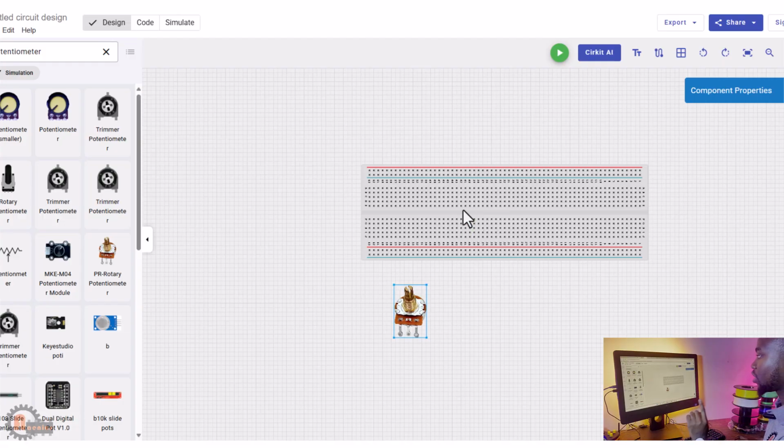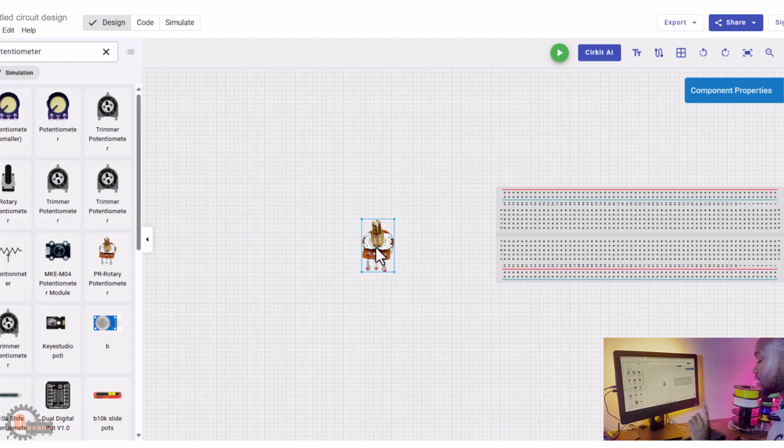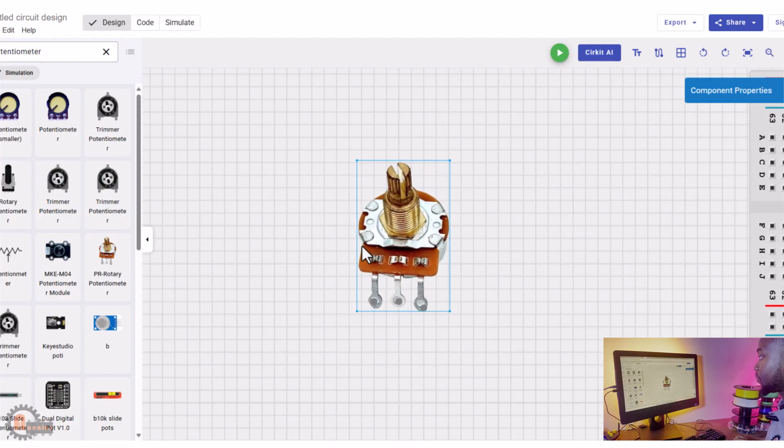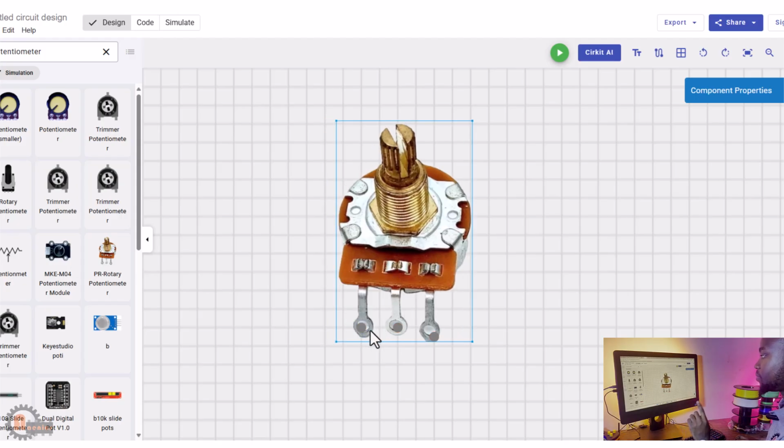I actually want to show you how the potentiometer works firstly, even before we attempt to use it to build anything. So if you take a look at the potentiometer, it has 3 pins. 1, 2, 3. Though there are labelings on each of these pins from this software, it's not really compulsory how they've labeled it, just that this is the way you find it most of the time. So the first one says ground, the second one is output, and then the third one VCC.